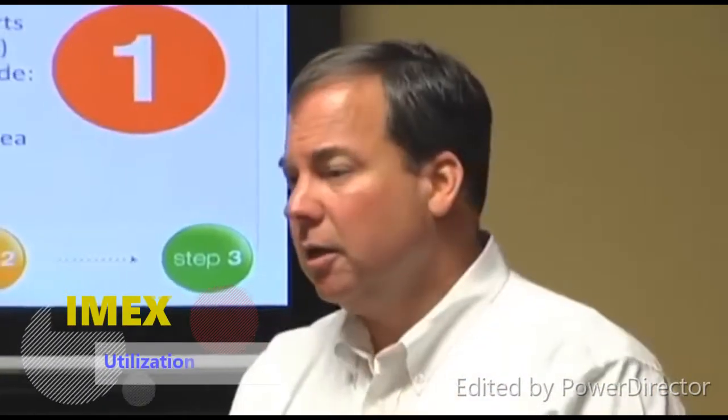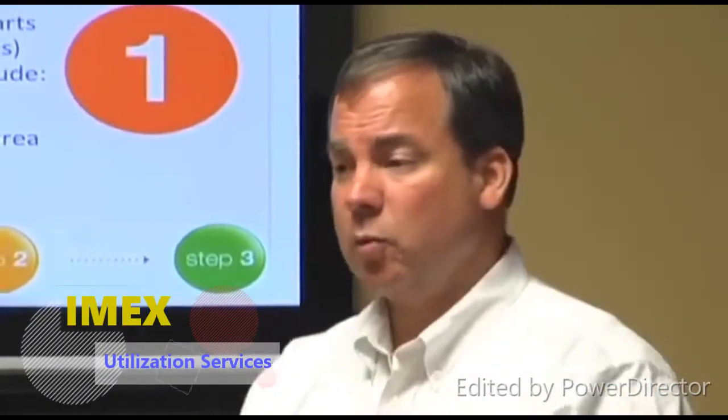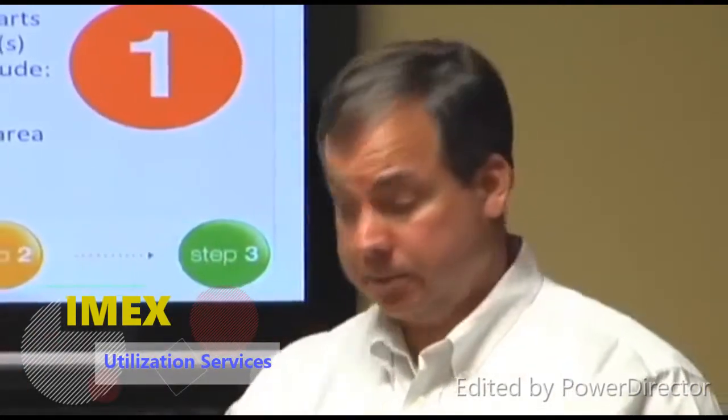We want to know what metal it is. Remember I mentioned there's some metals that you don't want to put too much protection onto because you can damage them. So we want to know what metal it is. Carbon steel? Is there copper in the area? Or do we have to worry about copper? So there's a lot of questions we'll ask about the structure we're trying to protect.